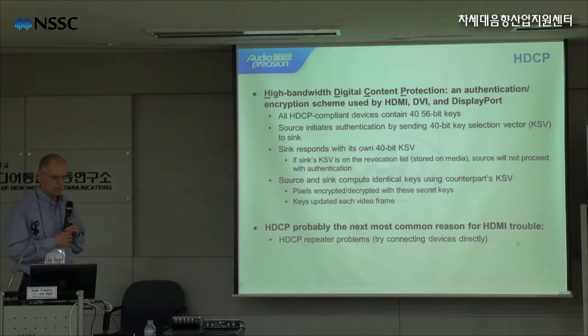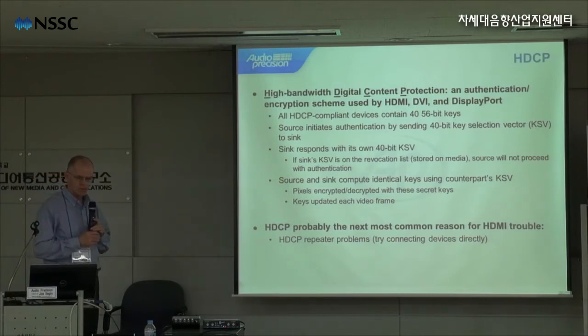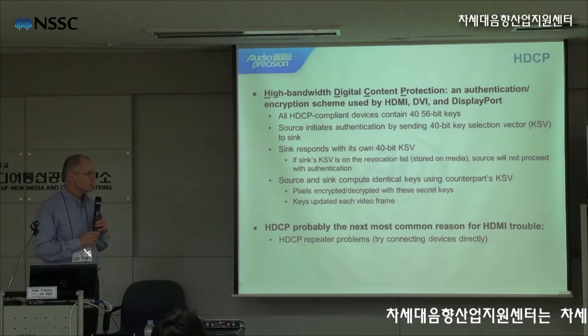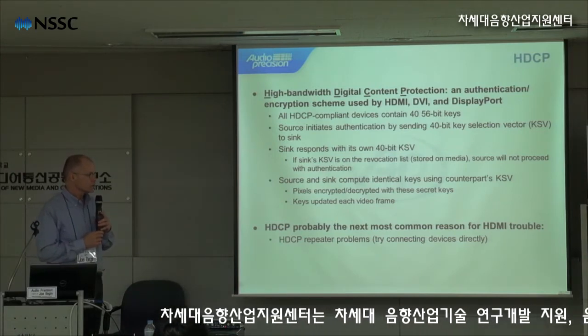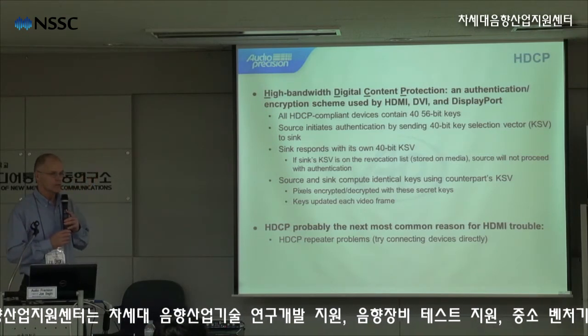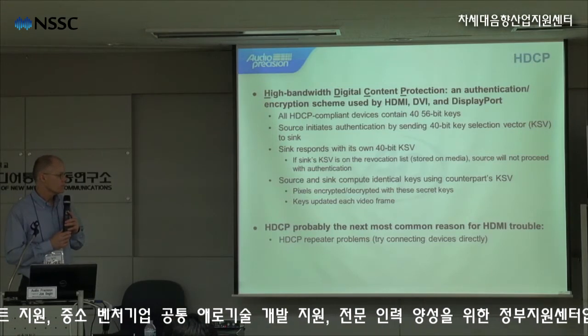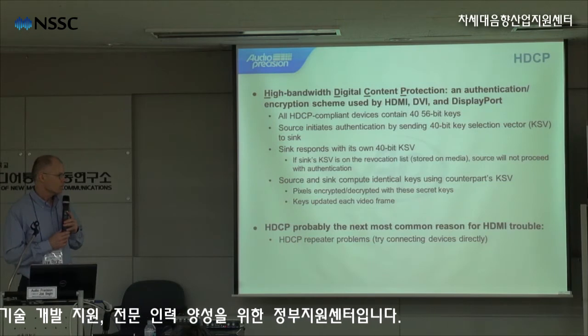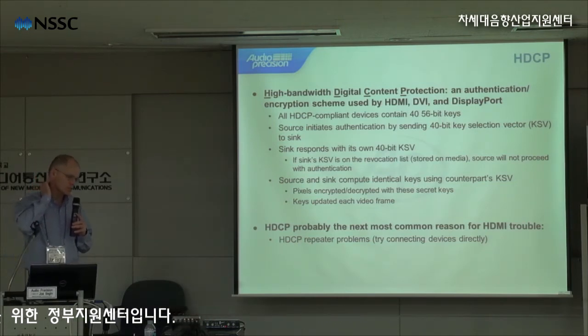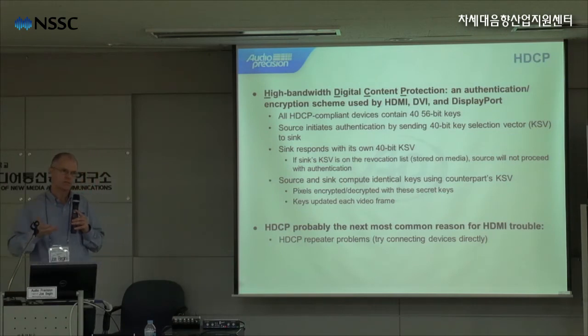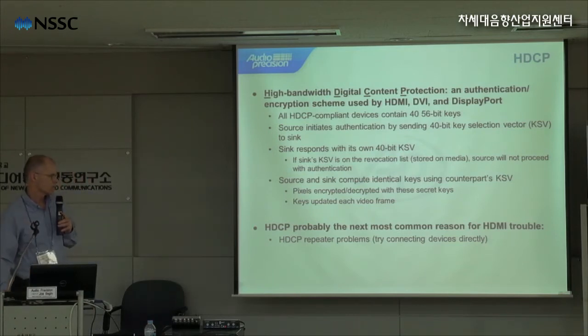So in the APX software, we have the ability to enforce HDCP, to enable it or disable it. We can also record audio streams from HDMI devices, but if they're encrypted, we can't record them. We're not allowed to by the HDMI standard. And this is one of the problems we've had with a lot of Blu-ray player manufacturers. They've asked us why we can't record the audio from their Blu-ray. And the problem is that most Blu-ray players enforce HDCP, and we're not allowed to record a stream if it's turned on.